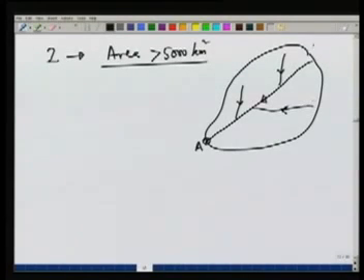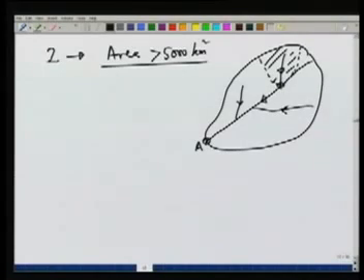So if we look at this area, we can subdivide this into smaller areas and then apply the unit hydrograph theory over the smaller areas. For example, if the catchment area of this tributary is like this, then this area being small, we may be able to apply the unit hydrograph theory for this particular tributary, find out the flow at this point, let's call it point B. So once we apply the UH theory over this shaded area, we can get the outflow at point B.